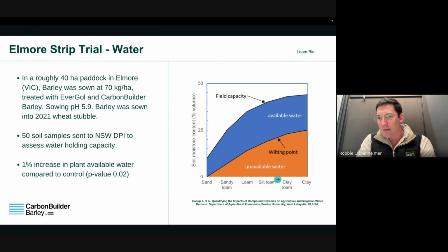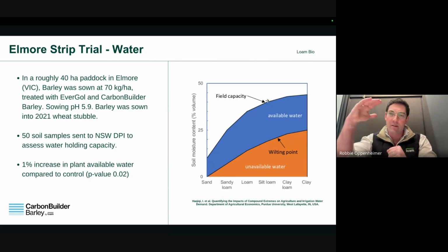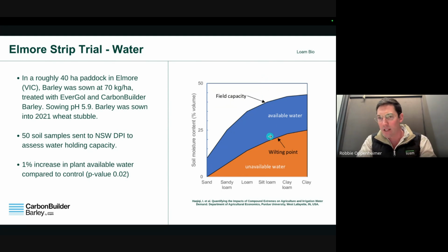So in the soil samples, we measured the permanent wilting point, which is the lower limit for available water, where basically a clay would hold onto that water so tightly that it's not available to a plant, and measured the upper limit, the field capacity. That's the point where a soil sample is completely saturated and you can't add any more to it. The difference between those two is the plant available water, which will vary at different points in the season depending on the amount of rain.